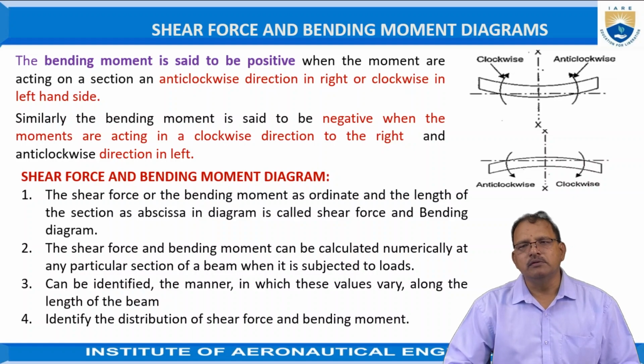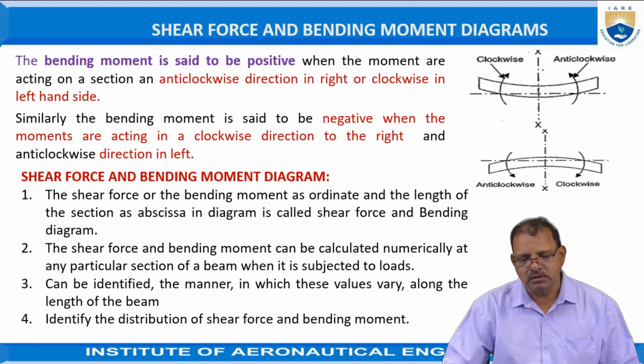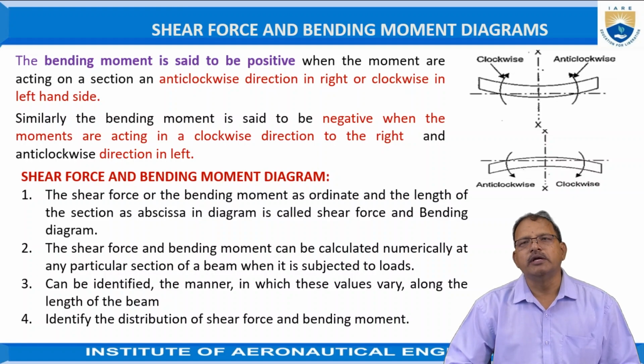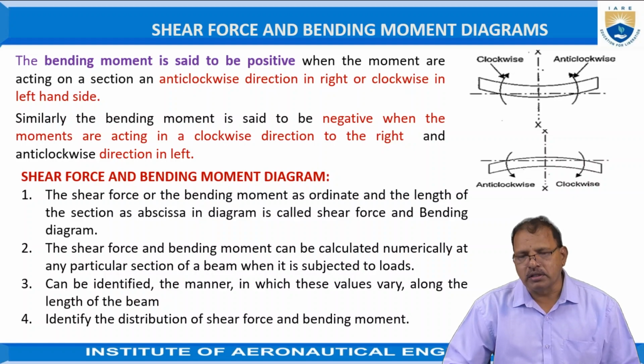Here, shear force and bending moment diagrams. The bending moment is said to be positive when the moments are acting on the section in anti-clockwise directions on the right side and clockwise directions on the left side.